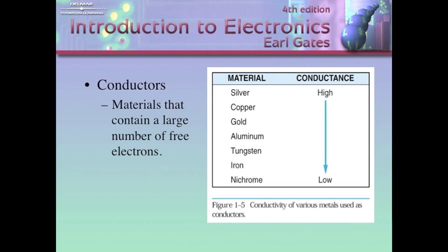Copper. Does copper oxidize? Yeah, copper oxidizes and tarnishes as well. So it's the same problem. Do we use a lot of copper wire? Yeah. And why do we use it? Because it's abundant, it's relatively cheap, it's really the best solution for us to move electrical energy from point A to point B. So it makes the most sense. And you could clean the copper to make the connection and make it work. Why do we see so much gold in the industry? It's expensive and it looks nice, but what's the real reason that we use gold plating on a lot of electrical conductors?